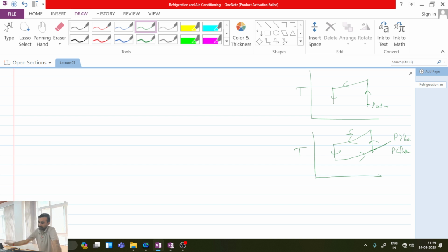Another important point is, whenever you are operating in a closed cycle, other than air, you can use any type of gaseous working fluid whose properties are commensurate with our requirements of the refrigeration space. Is this point clear or not? Okay, so instead of always using air, because in an open cycle, from where do I have to take the gases? Of course from ambient, and in ambient the only gas present is air. So if I have to operate an open cycle, I always have to operate it using air.